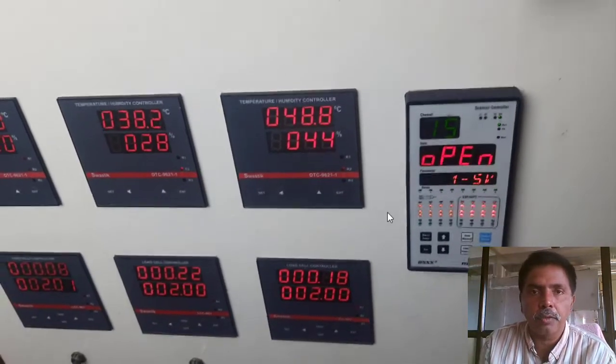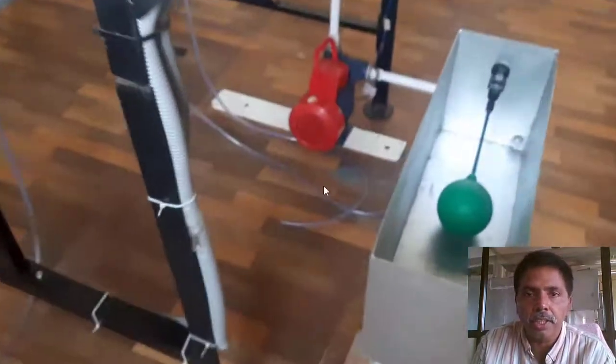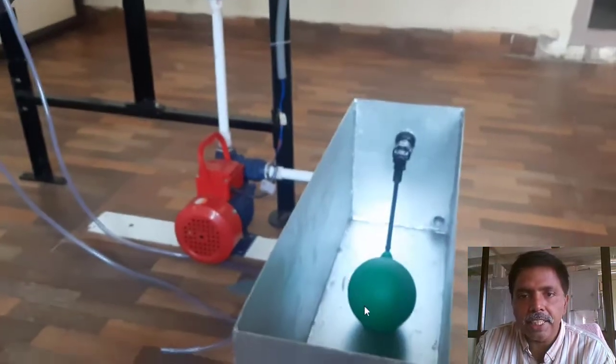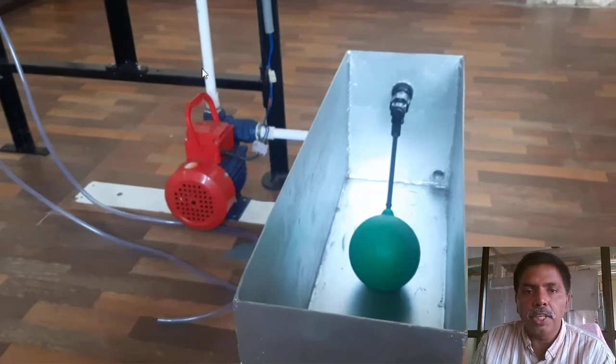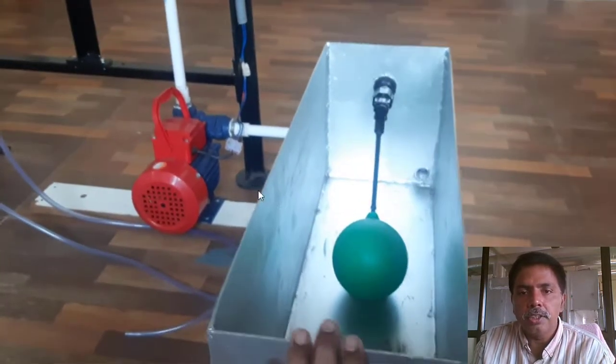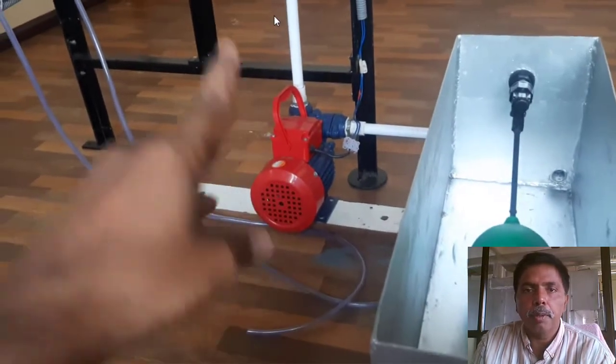This is the data logger. We are logging the data. And next, what is the load? What is the flow rate of the air? Why? Because removal of the moisture requires an artificial flow rate of air. You can see that for increasing the relative humidity, we circulate water using a pump. This is the sump. From the sump, the pump collects the water.